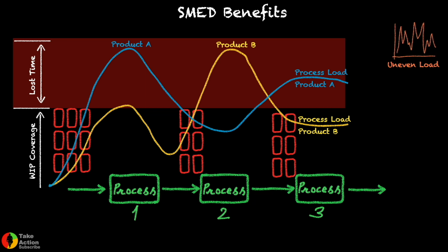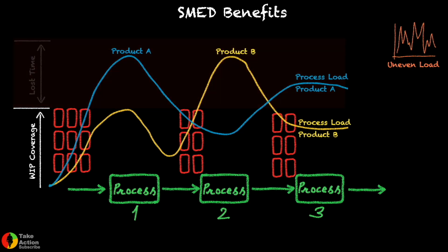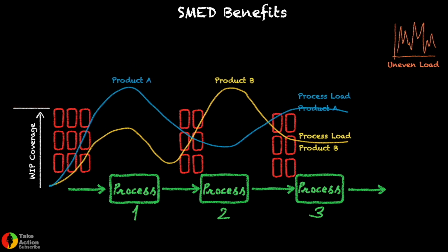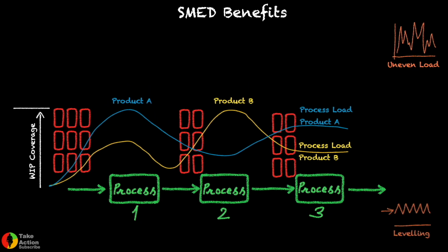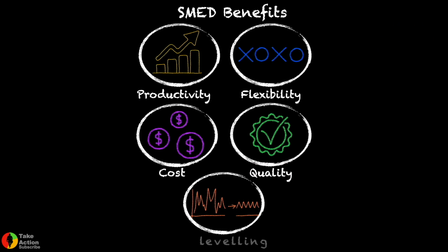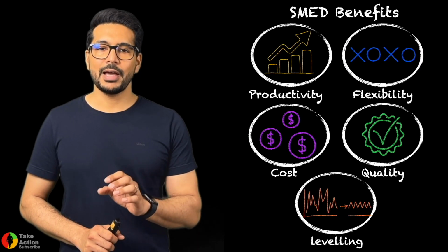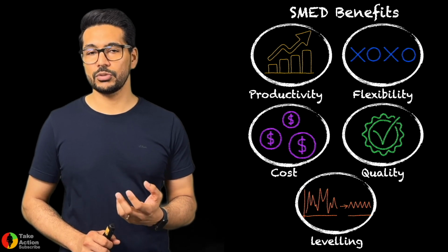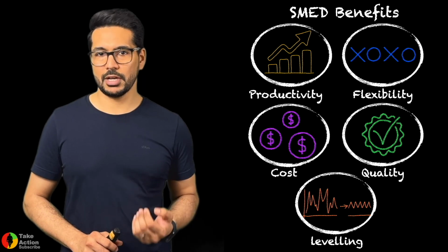So, and that lost time can never be recovered. But on the other hand, if we have smaller lot sizes, the bottleneck process will switch the production from process 1 to process 2 very quickly. And with that, the supplier and the customer processes might use their buffer in that time. So there are more chances that the supplier and the customer process are not running out of stock and they can produce continuously. That is also a very big benefit which is hidden, which is not very easy to recognize, which is delivered by the shorter lot sizes in the production.